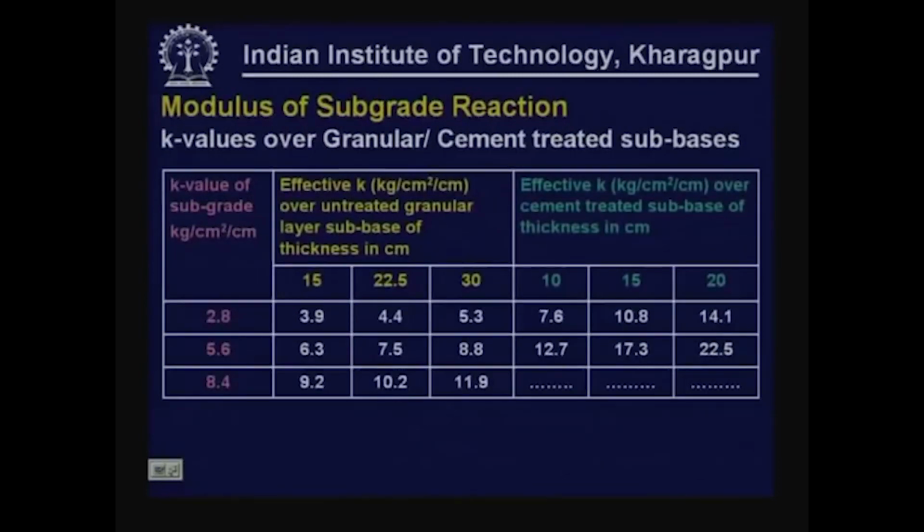But most of the time, especially for highways, we do not normally place the slab directly on the subgrade. So, we either have a granular subbase or granular base or a cement treated base. The cement treated base plus the subgrade forms the foundation. There is a slab, and below that you may have 1 layer, 2 layers, 3 layers. All these layers below the slab form the foundation. So, we have to have one equivalent parameter, that is the K value, representing the strength of all 3 or 4 layers that you have below the slab.